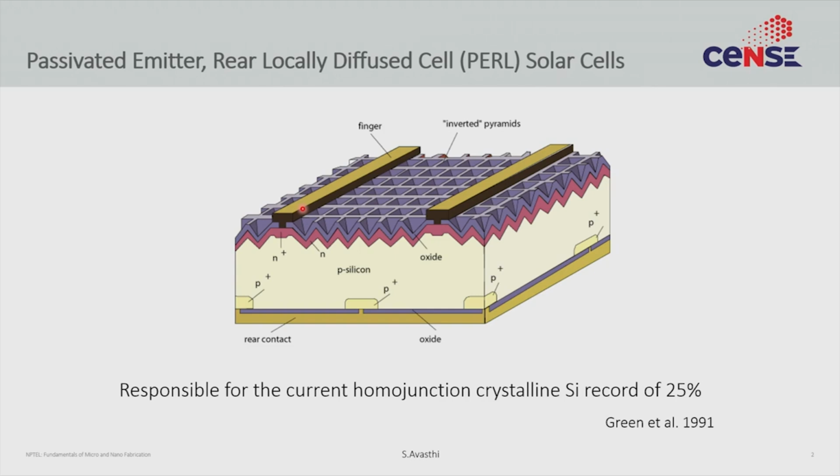Other thing you would notice is that we are starting with a p-type substrate, and this red represents an n-type material, so you can immediately see that there is a PN junction being formed. And this PN junction fundamentally is what is responsible for separating carriers and creating energy from light. Now, those are the simple things you would observe. If you knew a little bit more about devices, you would observe that there is not just p-type silicon, but there's another junction here, a p plus p junction, so highly doped p-type and moderately doped p-type. Such junctions help reduce recombination losses at the interface.